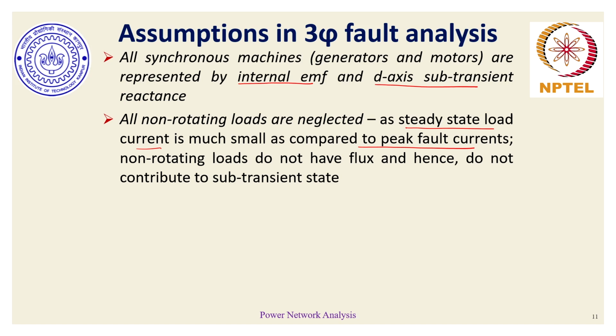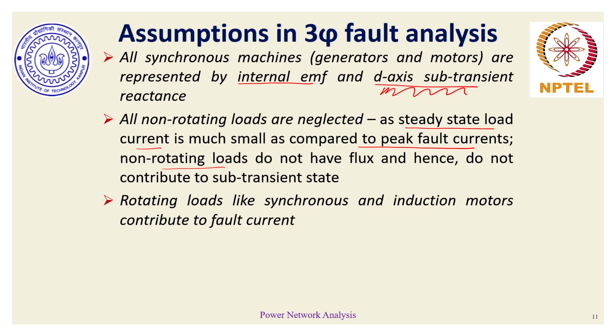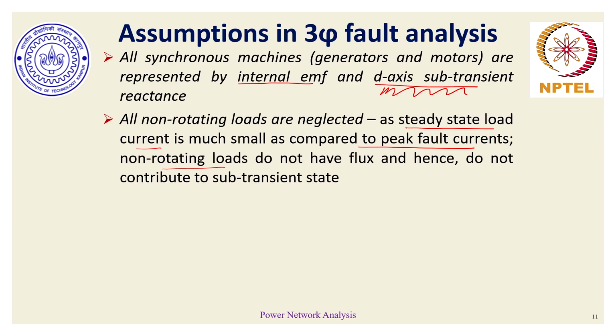Point number two, non-rotating loads don't have any magnetic flux, so essentially they won't experience any subtransient, transient or steady state variation at all, because there is no magnetic flux which is varying with time. Obviously, in case of transformers, the machine has a magnetic behavior, but there are no rotating devices involved at all.